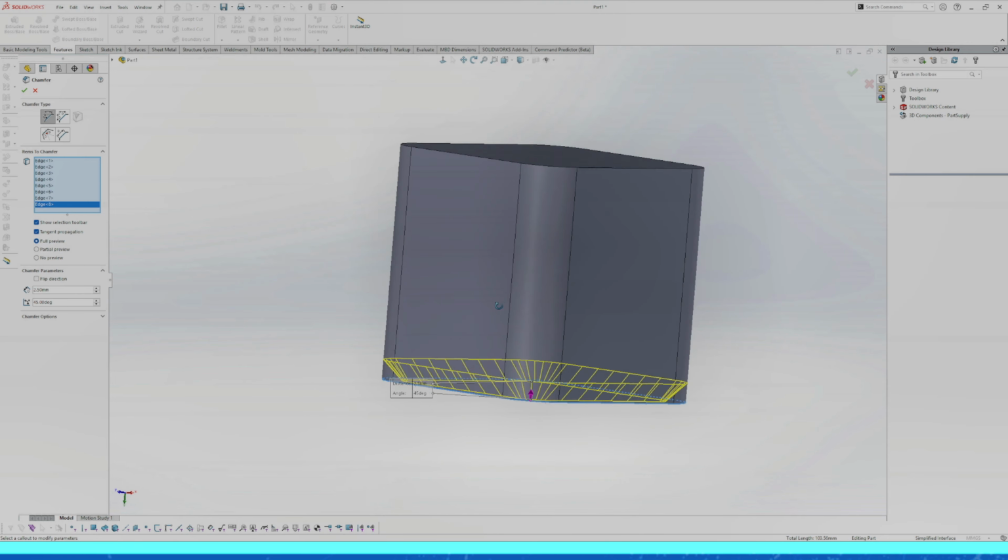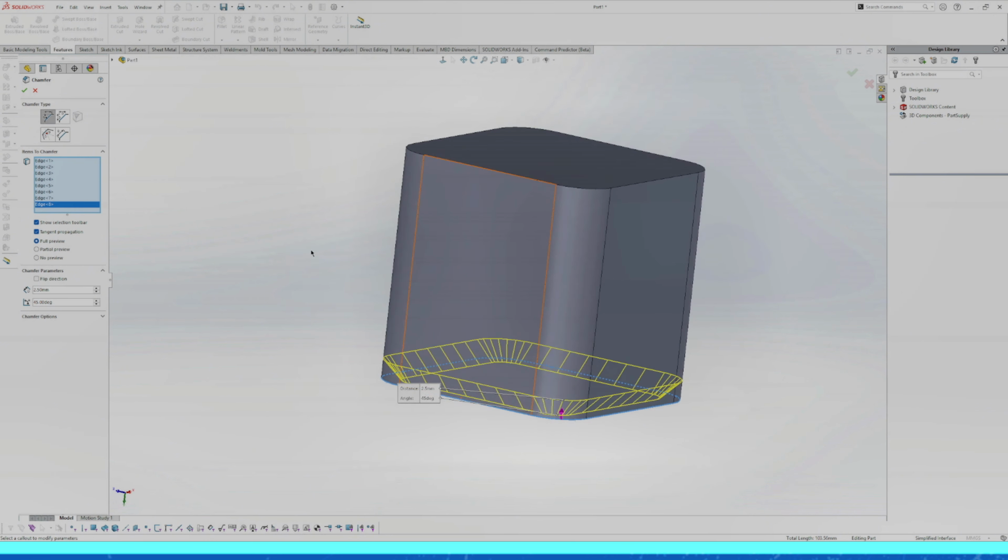That's typically the only chamfer you'll see unless you're doing injection molding. And those have what's called a draft angle. It's an angle that goes outwards, so it would be like negative 10 degrees.